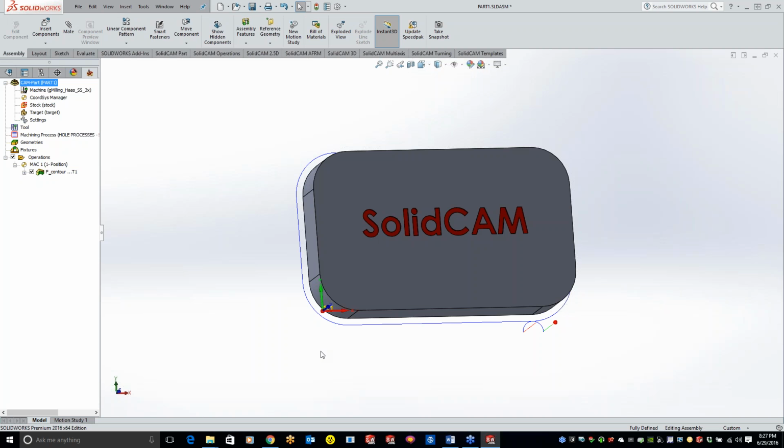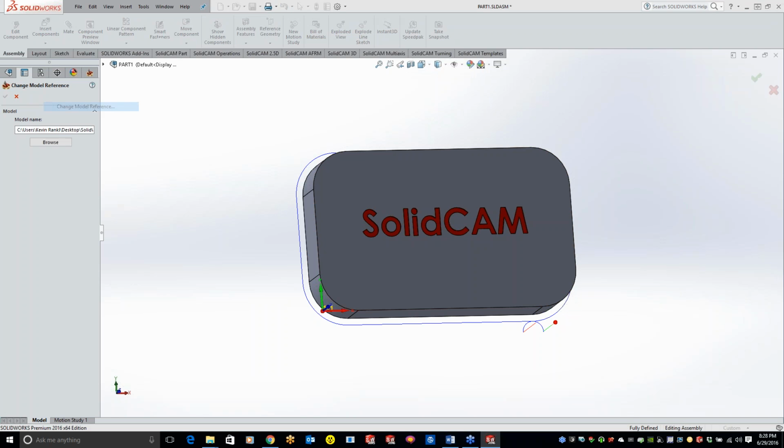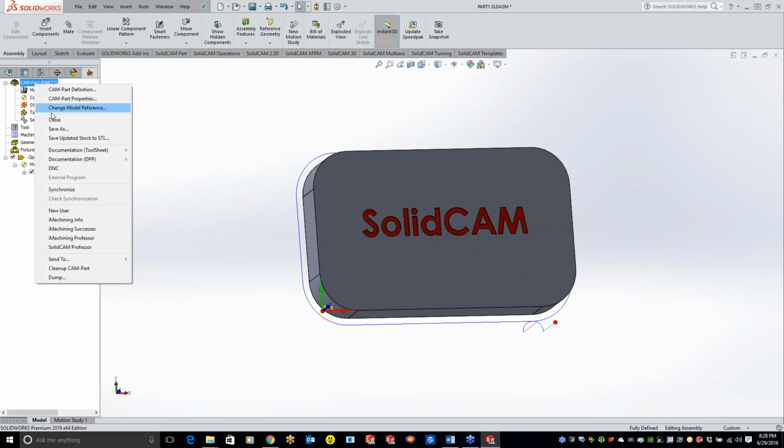So, Mike, hopefully that answers your question about relinking it. All you have to do is come up here and change model reference and browse to where that SolidWorks file has been saved for you. And that works with compressed or uncompressed. Now, as we roll into internal of SolidWorks, you won't be able to do this with internal, and I will show you why and what goes on with the internal of SolidWorks. So let's close out of this here.